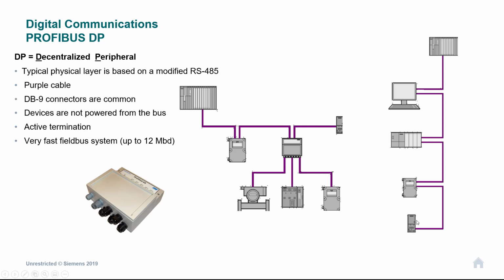And if you look at RS485, it is designed to be what we call daisy chained, which I'm showing you here on the left hand side. If you break that cable, say here where I'm showing now, you may think that you're just going to lose all of the instruments after that cable break, but unfortunately you've now removed the end of line termination resistor from the network, so you could lose the whole of the network.